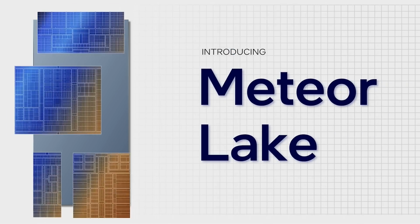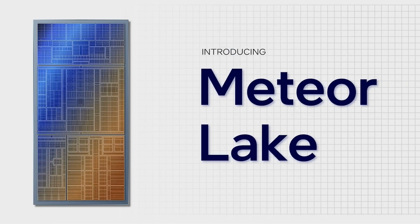Strategically, what we figured out is that not all IPs in the entire Meteor Lake need to be on the latest cutting-edge process. There is an optimization that you could do across power, performance, and cost vectors, and that gives us the ability to split the die into multiple tiles and tailor the IP for the process node that's best suited for it. What we were looking for with Meteor Lake was not a patched solution, but a solution that is scalable. Meaning that today I have, let's say, 3 agent IPs, but tomorrow if I have 3 more, will I have a design that can support this, or do I need to redesign?